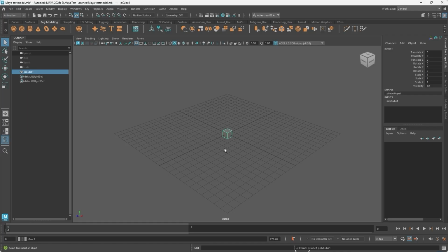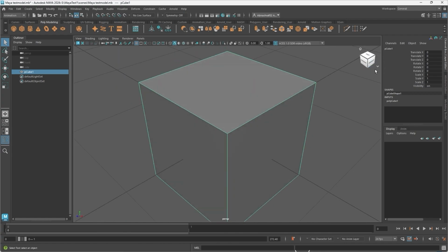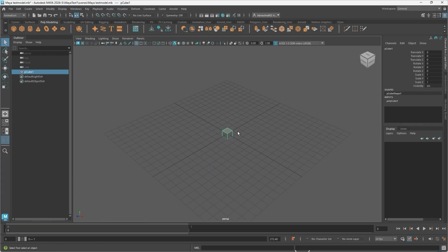Now, how do you navigate around? First, let's look at different views. So right now, it is our perspective view that we can change and move around, and this is our cube where it says front. If you click these icons, it will show you that angle, top, even the corners are acceptable. Now, zooming in and zooming out is your standard scroll.